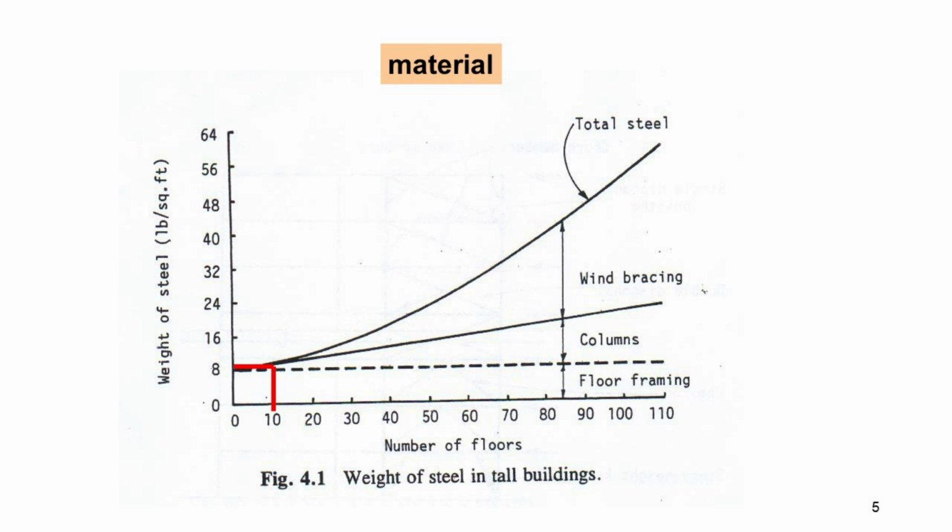A 10 story building can usually accommodate wind loading without any increase in weight of steel or member sizes. On the other hand, for buildings of more than 10 stories, the additional resistance increases non-linearly with height. That means for buildings of 50 stories and more, the selection of an appropriate structural form may be critical for the economy, and indeed the viability of the building.